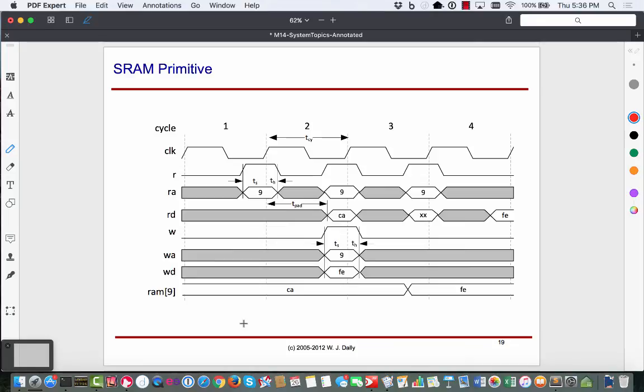DRAMs, which is what the main memory on our computers is made of, are much more finicky technologically. They require separate semiconductor processes. So it's relatively rare to find DRAMs sitting on the same silicon die as the rest of your logic. IBM has something called embedded DRAMs, and they come with compromises. So essentially the message I'm trying to give is that silicon processes which are used to make logic are not the ones which are well suited for DRAMs and vice versa. And therefore DRAMs usually sit separately, but SRAM can be put on your chip.